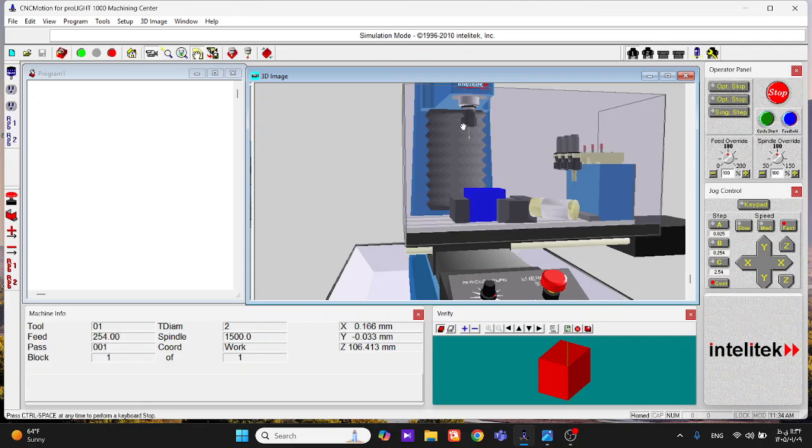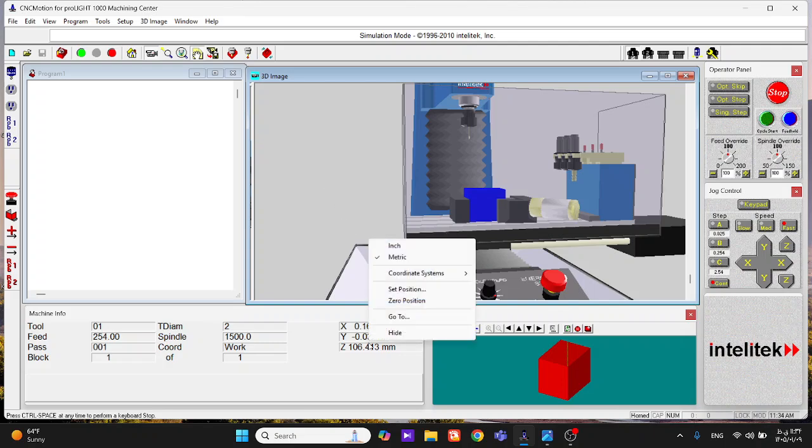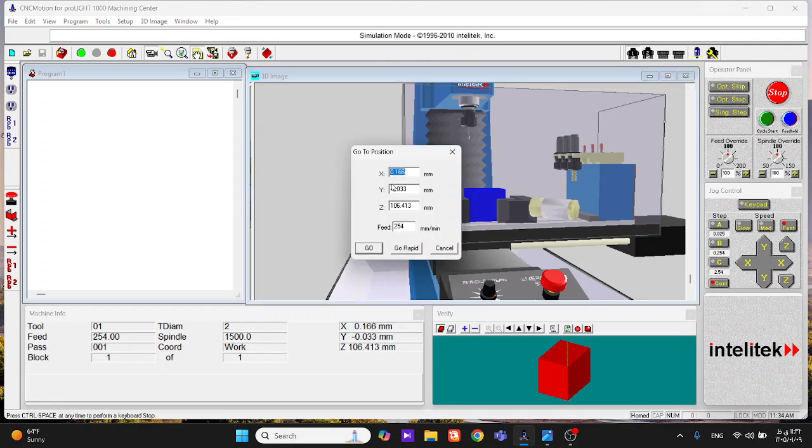Also, you can start while the arm and spindle are in this position, because immediately when you write the G00, it will come to your 0 position that you defined before, and it will start the process from there. Or you can make it get closer to that position and then start your program. It doesn't matter generally. But for here, I will say go to my own 0 coordinate.